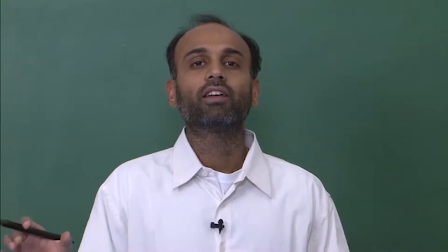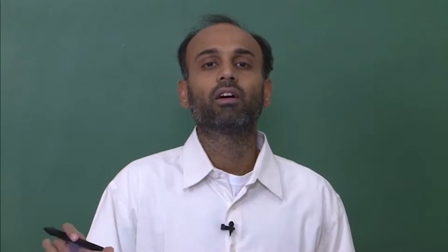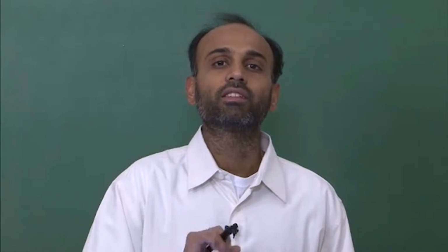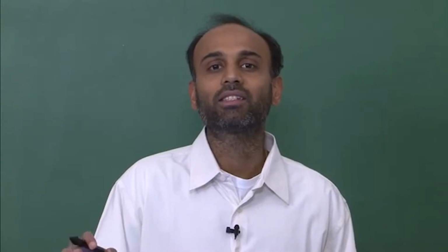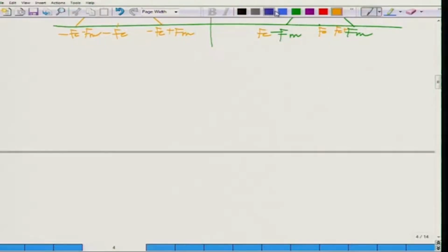So, what we have is that the baseband spectrum of m(t), that is M(f), is shifted to f_c scaled by half, and shifted to minus f_c scaled by half. What is more interesting is the spectrum of m hat(t) times sine 2 pi f_c t. So, let us look at that, m hat(t) sine 2 pi f_c t.